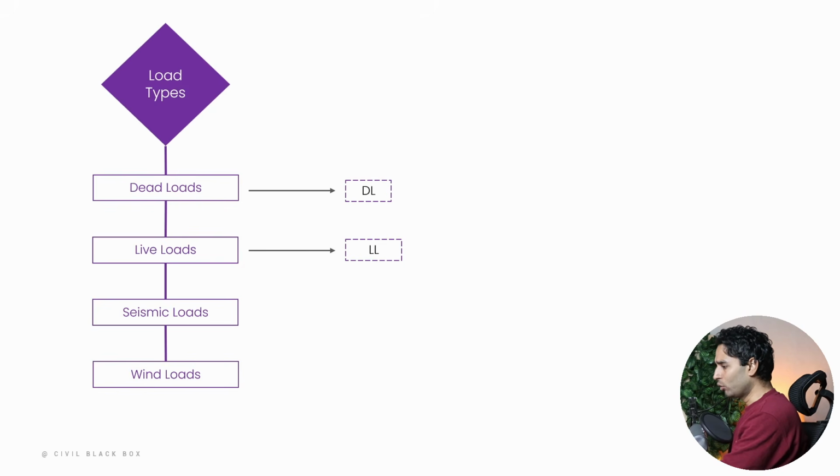When it comes to seismic load, however, we have different criteria. For seismic load, we'll be defining our earthquake load as something like this. So earthquake in the X with a factor of 1.5. I'll talk about it in a bit.